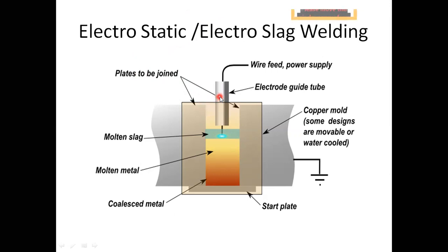And there are so many differentiations. We have to know which process is which. If you go for pressure welding, you can find these welding processes: first is the resistance welding process, friction welding process, diffusion welding process, ultrasonic welding process, cold pressure welding process, explosion welding process, and forge welding process. This comes under pressure type welding where we don't use any arcing. We just use some pressure and apply some heat so that it becomes a joint.